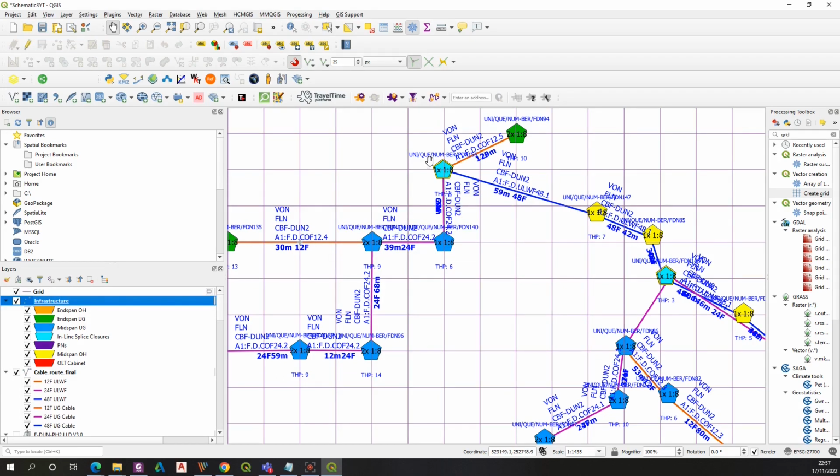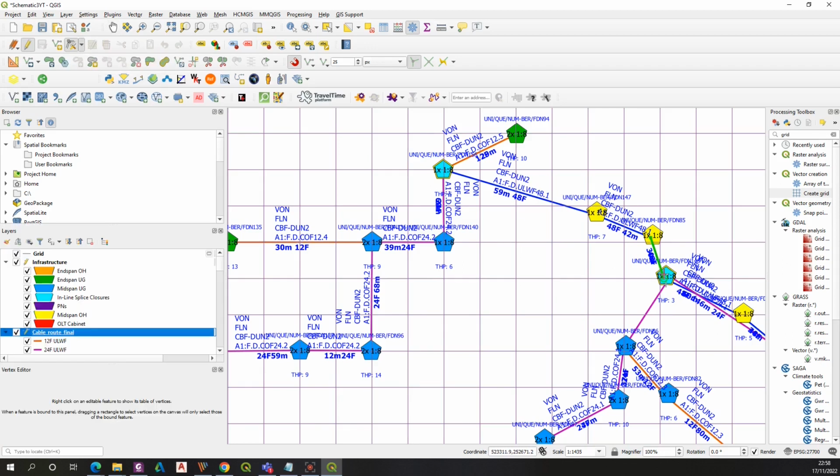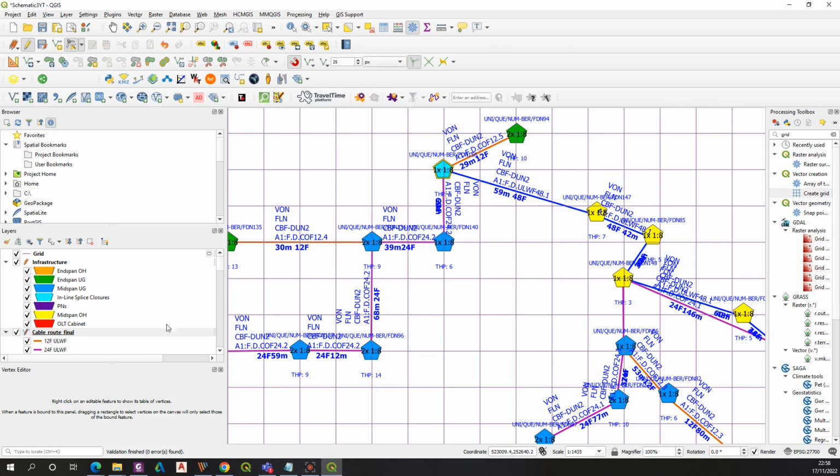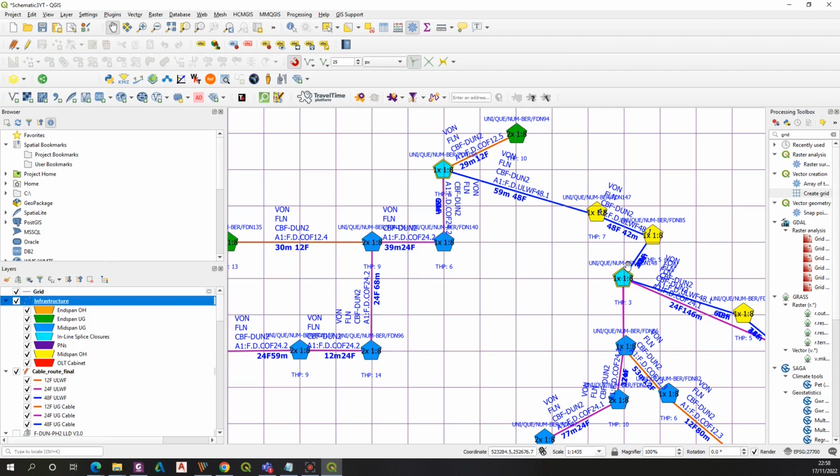As you may have noticed, where the point icon was doubled, it didn't disappear until you save the layer. So if a situation such as this occurs again, just simply save your layer and it will come out. Let me show you on the example also here. Like you see, the second symbol is gone, but if it has been saved, it comes out. Alright, so this is the way you can work on it.